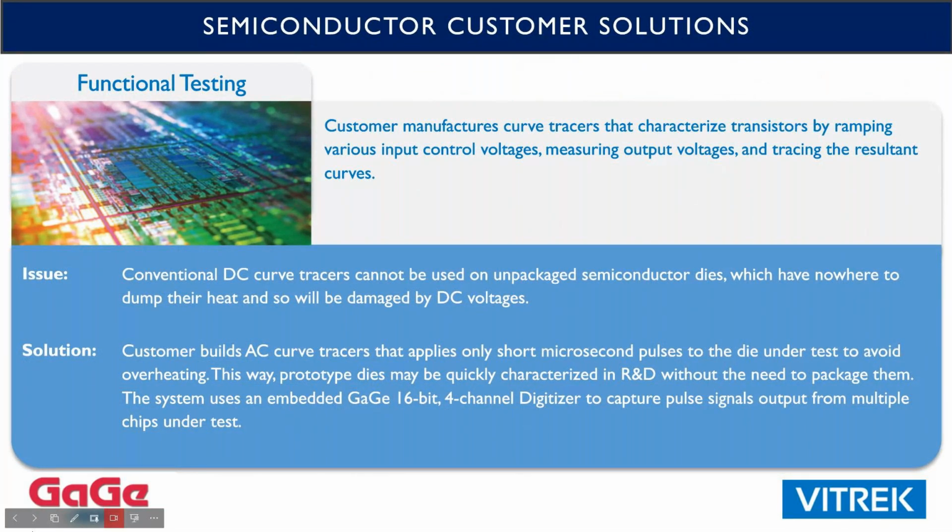So both sorts of read heads, the old coil and the magnetoresistive head, actually, it's interesting. I always assumed that a disk drive's inner cavity was evacuated to avoid air pressure. Apparently not at all. There's gas in there, because the head actually flies like an airplane wing, glides over the surface of the disk, and only flies at a couple of nanometers above the disk in order to get the greatest resolution. The closer you are to the disk, of course, the smaller domain you can write and read.